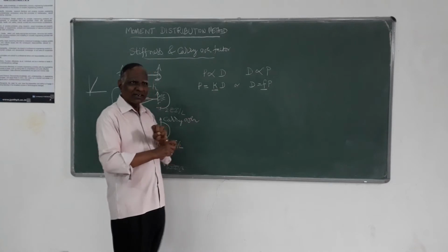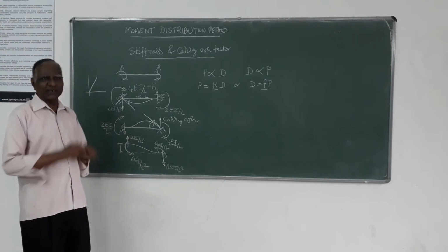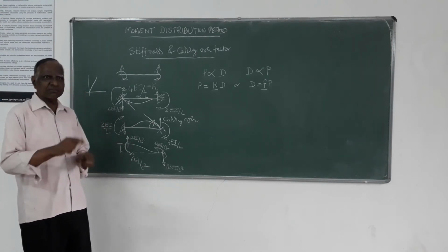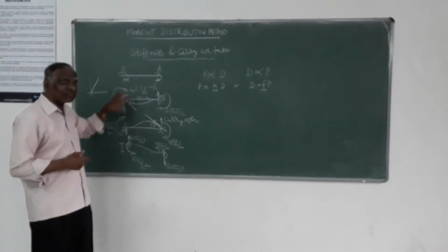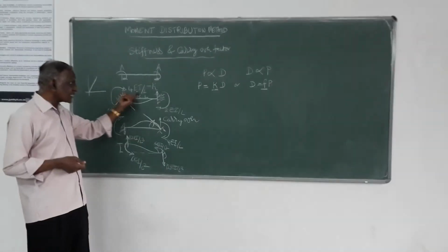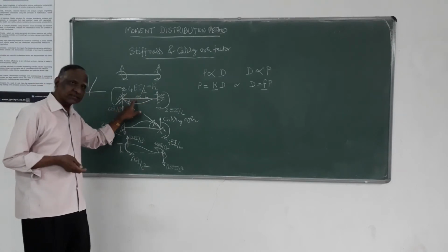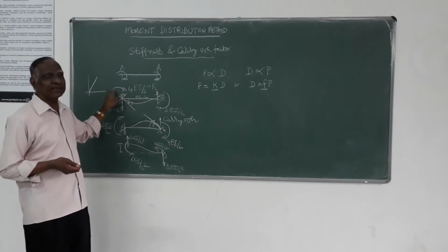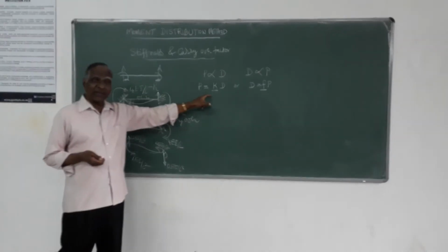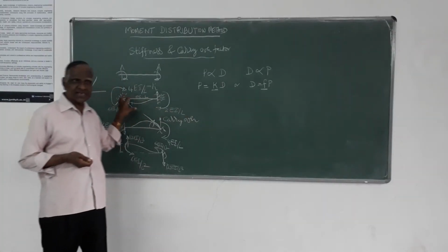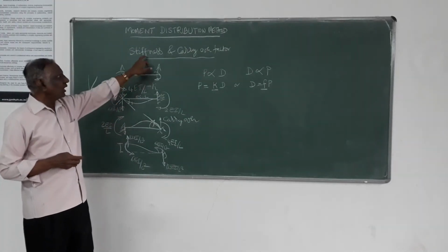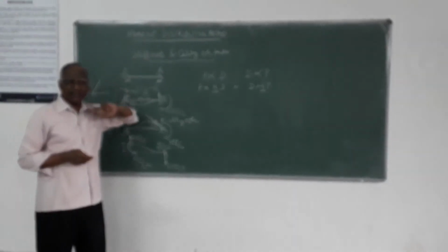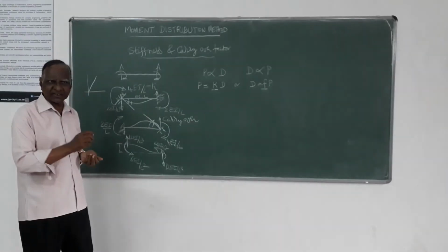This is the actual definition in loose terms. So stiffness is nothing but force due to unit displacement. Flexibility is displacement due to unit force. I have derived K with reference to expressions, with reference to geometrical properties like I, L and material property. This is the exact mathematical expression of stiffness and carry-over factor. Of course, this I have already circulated as a note.